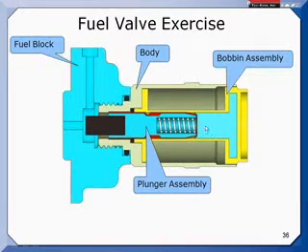And this is an iron core that is molded inside the bobbin. So when you energize the windings here, this becomes a very powerful magnet. And it draws this piston to the right, so this valve opens. And when you take away the electricity from that coil, the spring closes it.